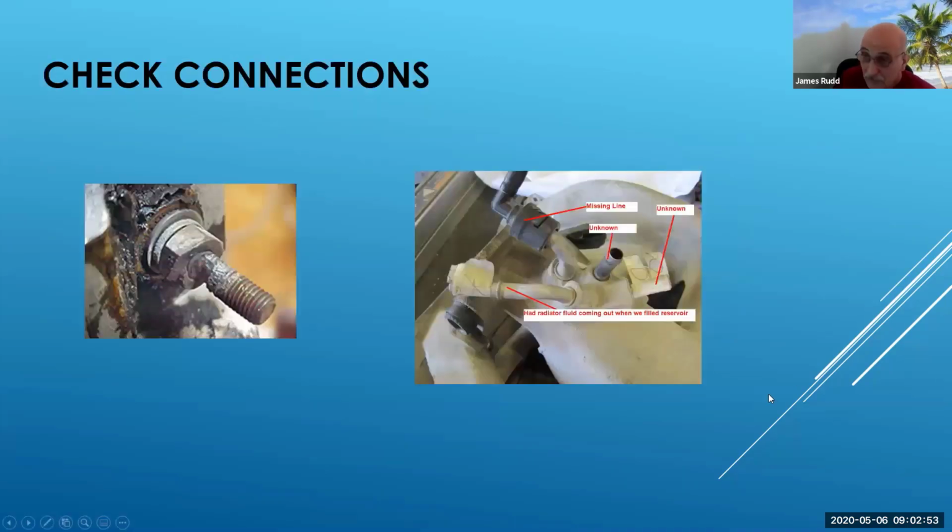All right. And then connections, like I said before, this is kind of over illustrated, but it did come from an actual vehicle. And this was a poor connection for a long period of time. And that poor connection actually caused some arcing. This is one of the main battery feeds onto a ground stud, and it just kind of arced itself away.